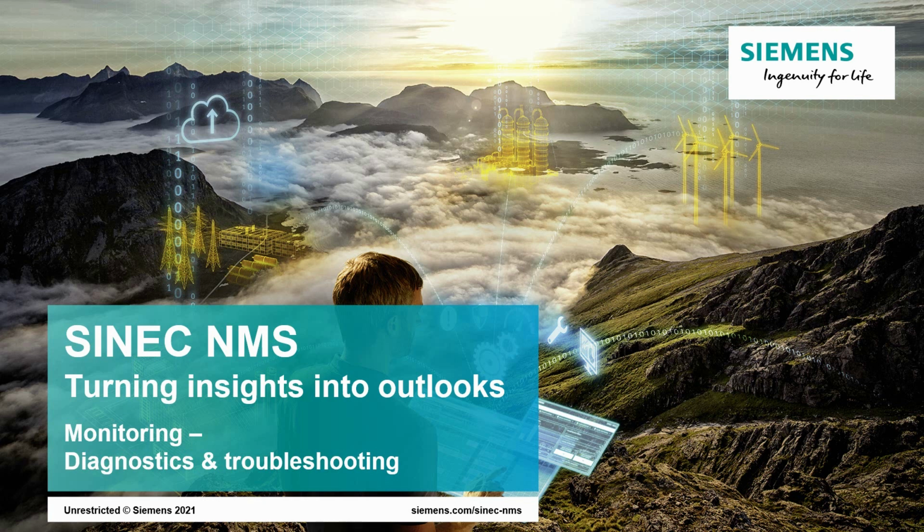Thanks to SINEC NMS, we have our system events, but of course also our network events, summarized centrally in one place. This means, among other things, that we can predict downtimes in our plant, and of course also see how our devices have been working in the last hours, days, or weeks. That is, whether or not they were 100% available, or whether they had too high an interface load somewhere. The obvious advantage is that we can reduce downtimes in the long term, and also increase the performance in our network.